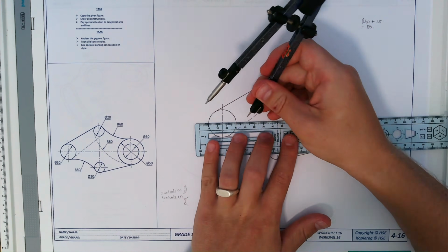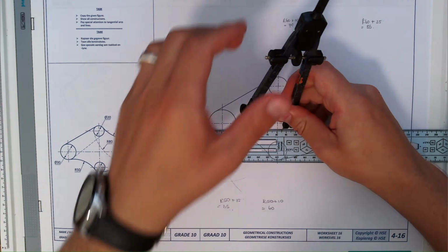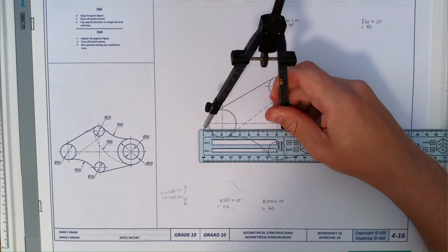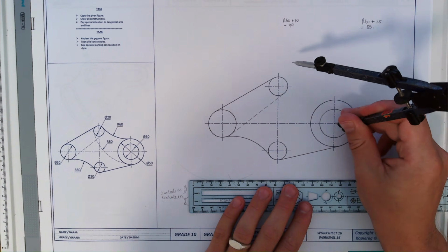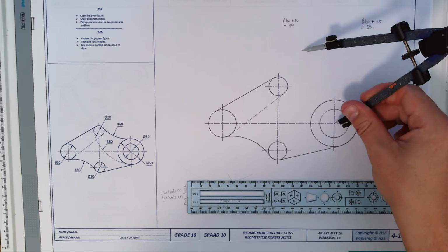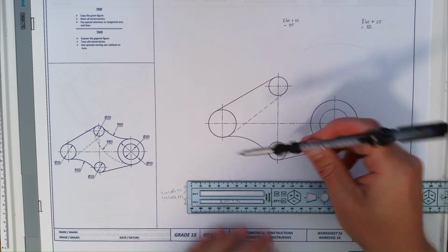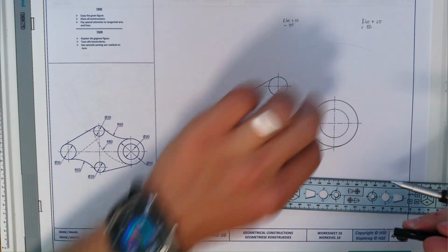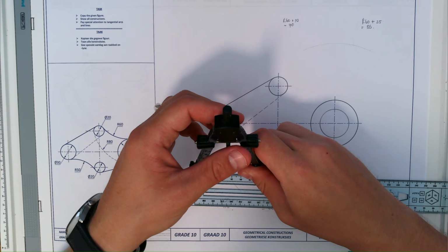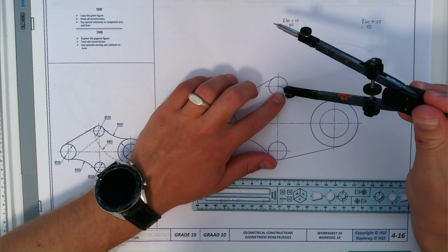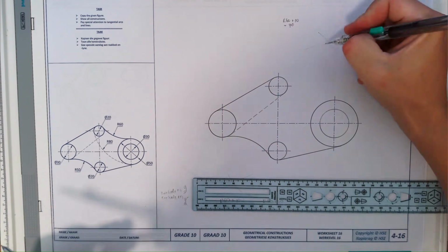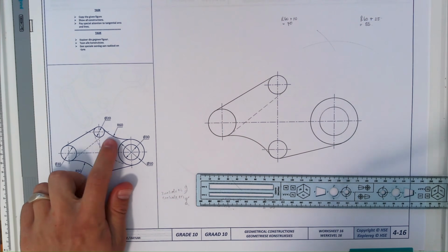So we're going to take our compass again, put it on 85. In the middle of the circle, draw a light arc in construction. Now I'm going to put it on 70 from the little circle because that is what we've calculated. Put it in the middle point, construct an arc, and there's your X. That's your point. Now I'm going to set this on the 60.